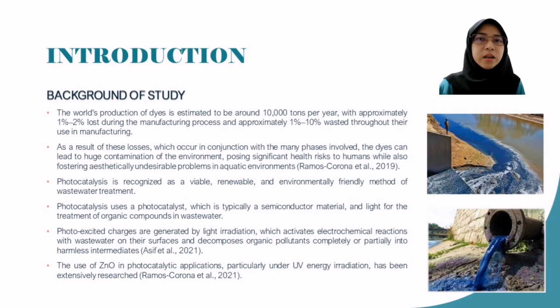Photocatalysis is recognized as a viable, renewable, and environmentally friendly method of wastewater treatment. Photocatalysis uses a photocatalyst, which is typically a semiconductor material, and light for the treatment of organic compounds in wastewater. Photoexcited charges are generated by light irradiation, which activates electrochemical reaction with wastewater on their surface and decomposes organic pollutants completely or partially into harmless intermediates. The use of zinc oxide in photocatalytic applications, particularly under UV energy radiation, has been extensively researched.